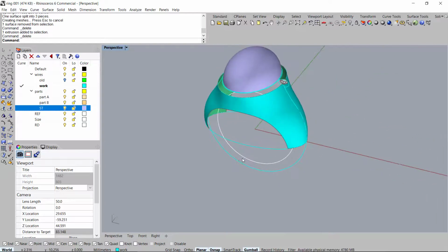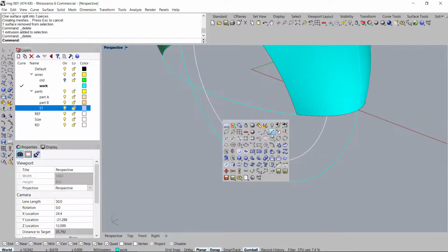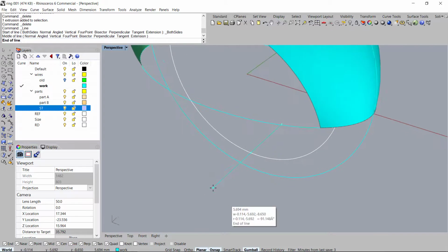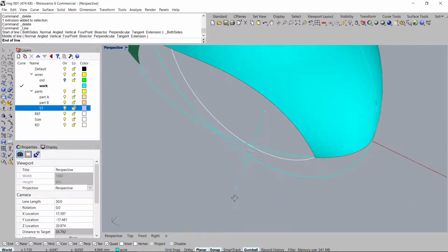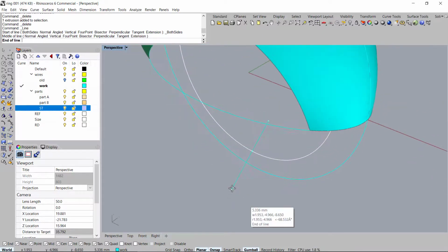Now the most important part of creating the final part of the shank is to determine the width of the bottom. Okay, so what I usually do is I know for a fact that the spring guard that I use can go anywhere between 1.5 to 2 to as much as 4 millimeters wide. That's a 2 by 1 millimeter stick. So I already know that I want to use a 2 millimeter spring guard, and the thickness of the metal will be 1. So automatically I will just go with 4. So just type in 2.